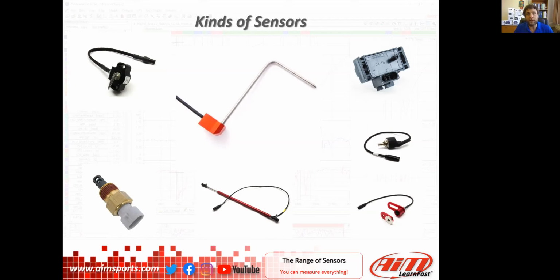Some really good questions I see popping up, things about fuel flow sensors. Another great question, if it outputs a voltage, it will follow through here just like we're looking at. Another one about voltage, if we can take 12 volts, that's when the systems can take in the 12 volts. Most sensors are 0 to 5. We can work 0 to 12. And then asked if the voltage drops below 12 volts. Well, that comes down to a sensor question, how sensitive the sensor is. Many sensors are only a 5 volt input, and we have that in the wiring as well. So it's kind of specific.